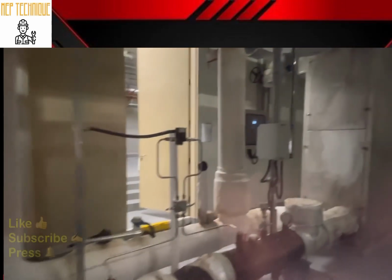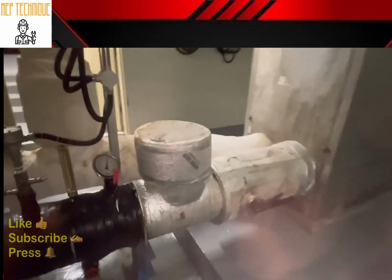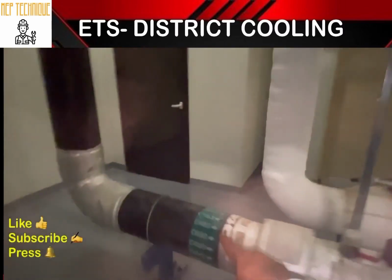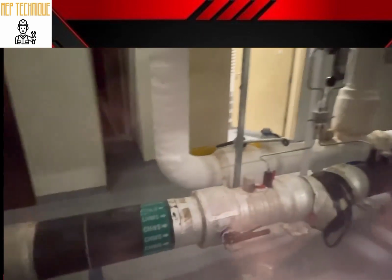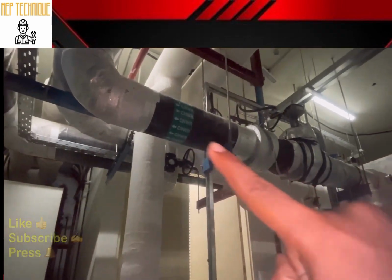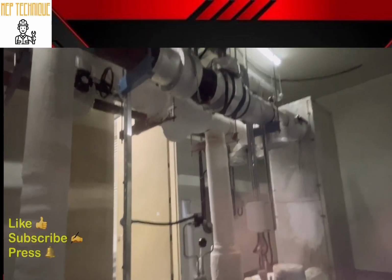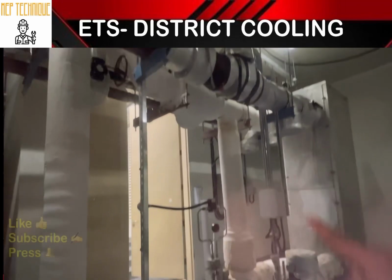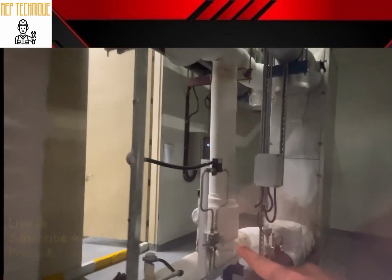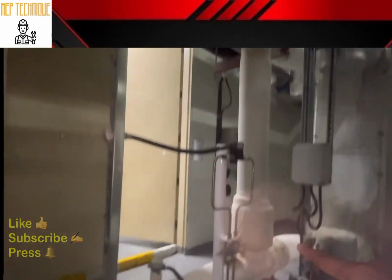In the primary circuit, this is the chilled water supply. You can see here, this is the chilled water supply line, connected to the bottom side. This is the chilled water supply, and this is the chilled water return, connected to the top of the heat exchanger. This is the supply, this is the return, and this is the primary circuit. And here also you can see the white line. This is the supply and this is the return of the secondary circuit.